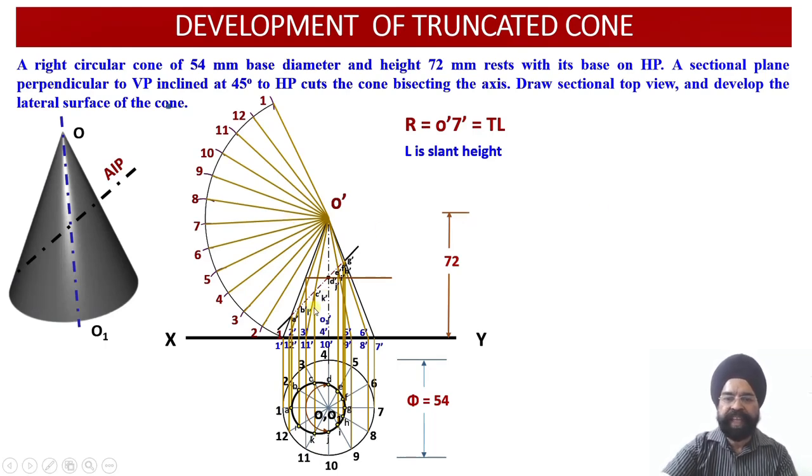Then what about the remaining 10 points over there? So let us start working it out. I have drawn the first arc starting from A, and as I have just told you, O dash A dash happens to be true length. So since this is true length, all these arcs should be true lengths only, and no apparent length arcs should be drawn over here. I'll mark this point as capital A because I am starting from 1 and ending at 1, so point A will be available at 2 points. Please check, A point will be available here and here. Now I have marked A points twice.